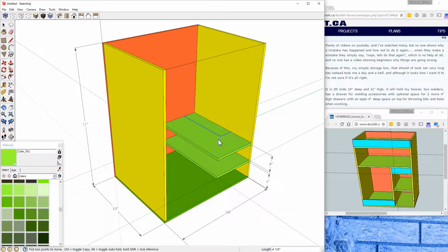And what you can see here is that as I drag the copy up and let go, it's snapping to a line, and therefore it's in the wrong plane. So drag it up, hit copy, and because my cursor is right near that line, it's snapping to that line. So I'm undoing that to get rid of that.